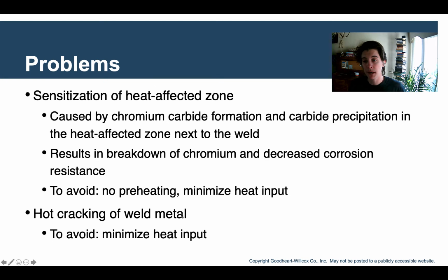So no preheating can be helpful. Minimizing the heat input is generally a good rule to follow. Anything you can do that minimizes the heat input is good. Hot cracking is a big problem with stainless steel. Again, minimizing the heat input. So lots of clamps that you can use. Do whatever you can to just keep that heat input as low as possible for stainless steel.